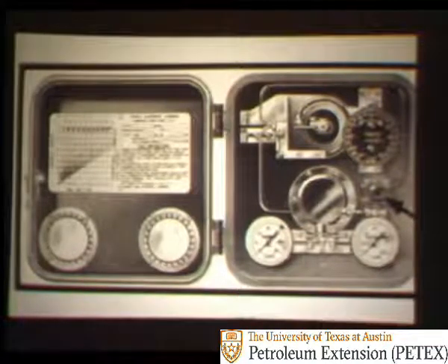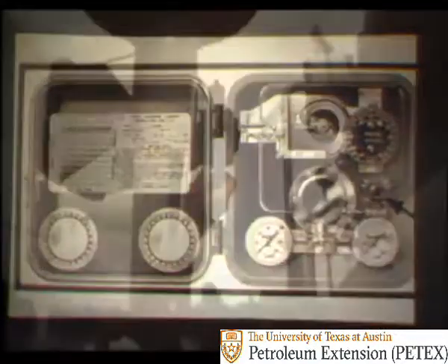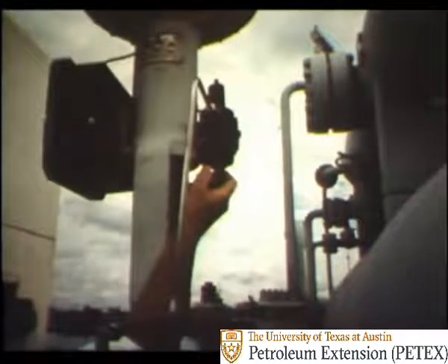Pneumatic controllers often have additional features, such as proportional band and reset. Their functions and operation will not be discussed in this presentation. These adjustments should be made only by a qualified instrument mechanic. As operators of this equipment, you will normally be required only to adjust the control set point. Each controller is equipped with an air filter regulator to supply clean air at a constant pressure for control operations.